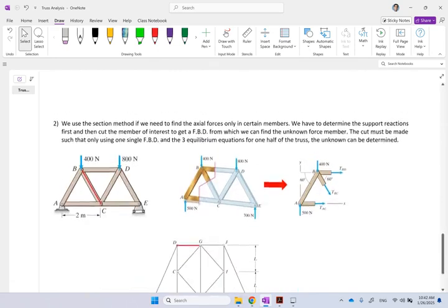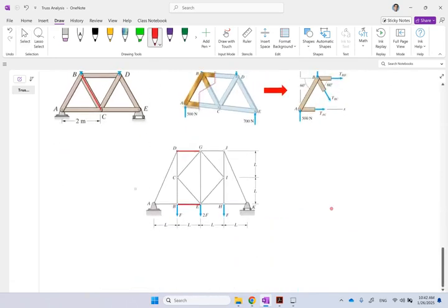And if you look at another example, let's look at this one, for instance. Is that also following the same thing? Here, you have 3, right? And then another 3, 6. So we have 6 along the triangles. And then we have 4 here on this square. So J here is equal to 10. And if we look at the number of members, right? Here we have 1, 2, 3, 4, correct? And then 5 and 6, and then 7 and 8, 9, 10, 11, 12, 13, 14, 15, 16, 17.